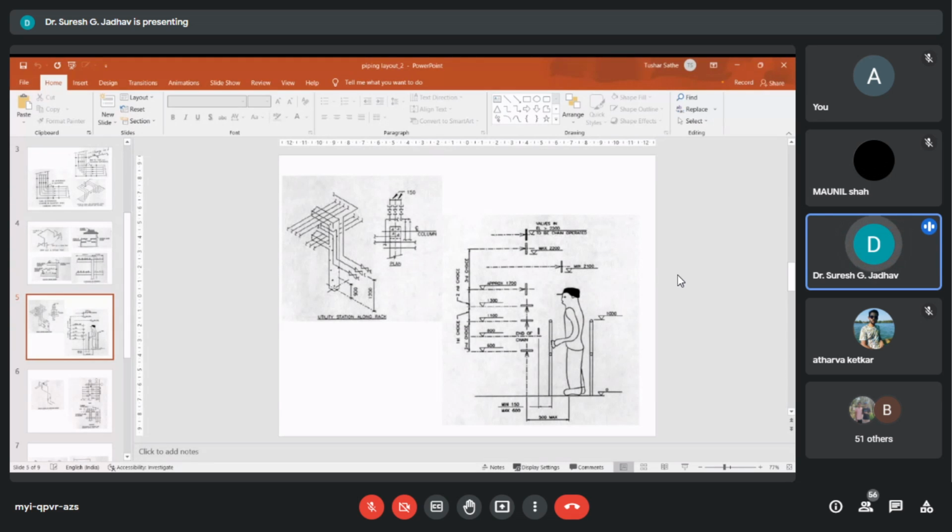Therefore, we have to consider that utility lines have two groups of valves. One group is closely related to process and should be located with accessibility just like process valves. The other group contains all isolating valves such as block valves on headers, root valves on subheaders, and valves for future connection. These valves are seldom used and are located overhead. Temporary ladder accessibility is acceptable for such valves.